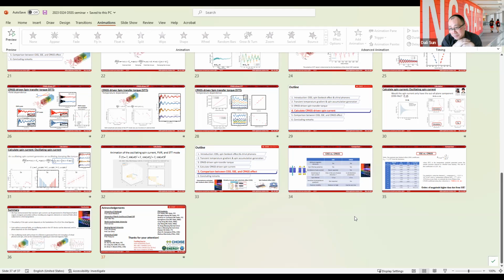We didn't do thickness dependence, typically because of materials limitation. In order to have a very well defined, high quality hybrid perovskite thin film, we have to adopt the solution process recipe. That recipe was always optimized for around 100 or 150 nanometers. If we reduce or even increase the thickness, the crystallization, the polycrystalline formation, and the domain size will be dramatically different. So the answer is we didn't do the thickness dependence. I see, okay, thank you.